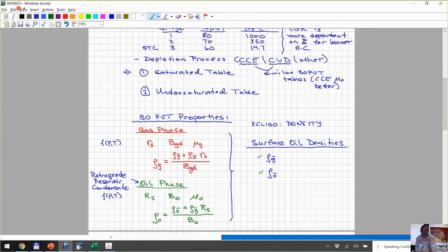We normally use the CCE ourselves for gas condensates, mainly because of the oil viscosity issue. If you use PVTP and they don't let you use CCE or CVD, then you won't be able to check it. But if you use another software that allows you to run CCE or CVD, you'll probably find the gas properties don't change very much at all.